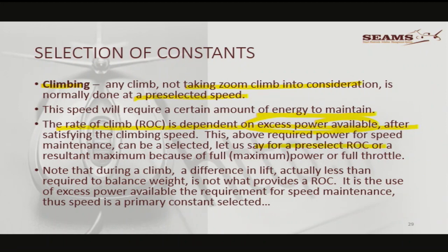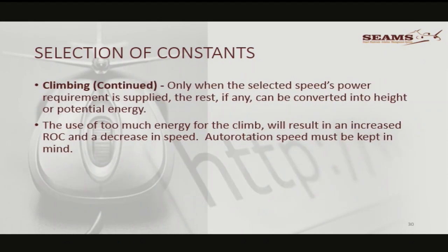Or you can say, look, I want to have a specific rate of climb. Note that during a climb, a difference in lift, usually less than that required to weight, is not that which provides rate of climb. It is the use of excess power that gives us the ability to climb. Okay.